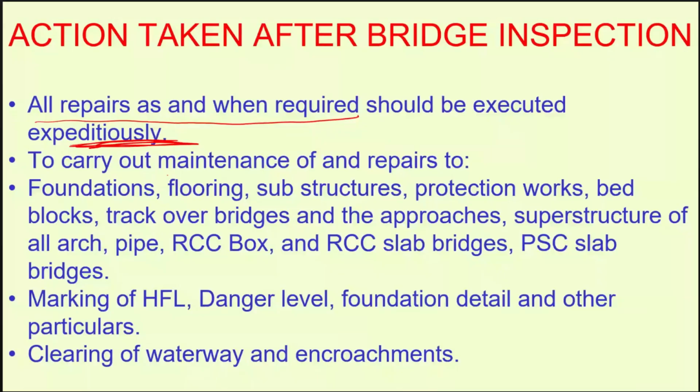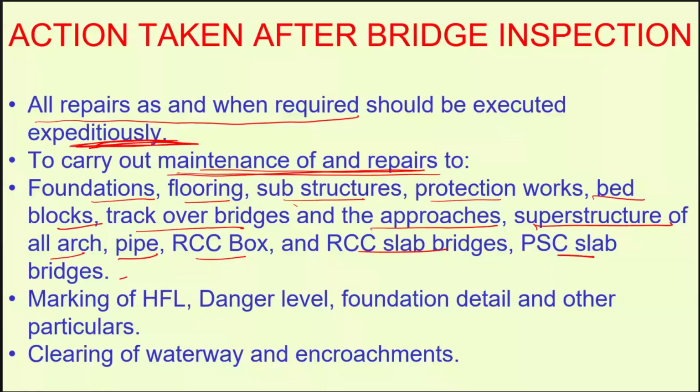Foundation, flooring, substructure, protection work, bed block, track over bridge and the approaches, superstructure, arches, pipe, RCC box, RCC slab, PSC slab, composite, all bridges, all the locations we need to see, and then we need to observe what repair and maintenance activities are needed.